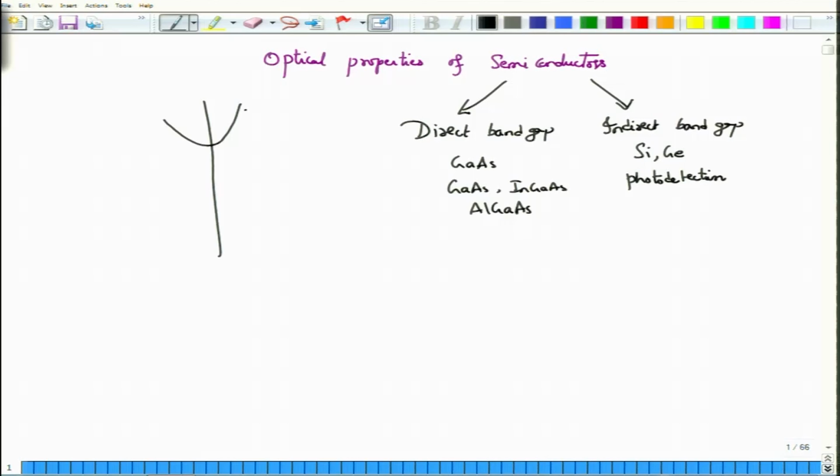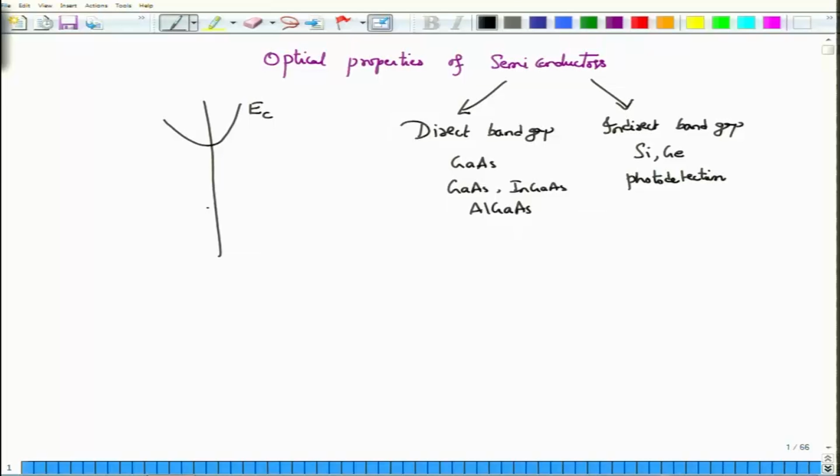So you have the conduction band not actually flat as we have shown, but that flatness is actually along the length of the crystal. What we are going to plot in this one is, on the horizontal axis, the momentum vector k along a specific direction. So, for example, for gallium arsenide, this might be the direction, the crystal axis as we would call it. Along this crystal direction, as the momentum keeps going, this is how the energy versus k diagram would look. For a direct band gap material, this is how the energy band gap would look roughly.